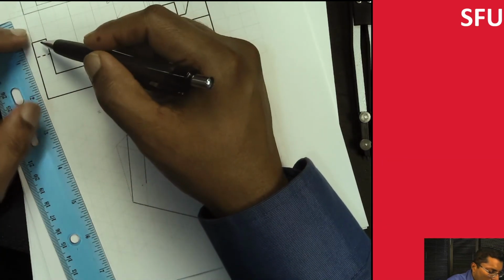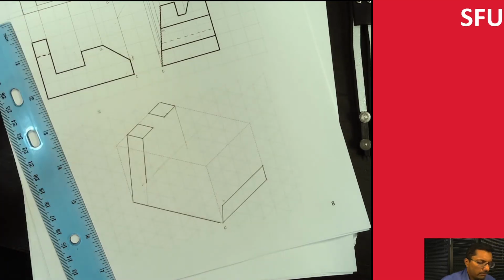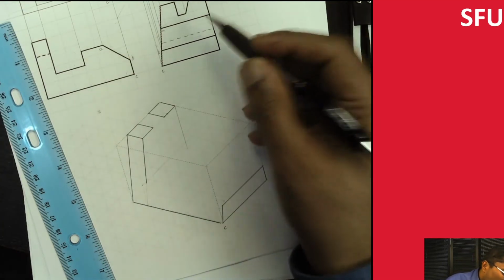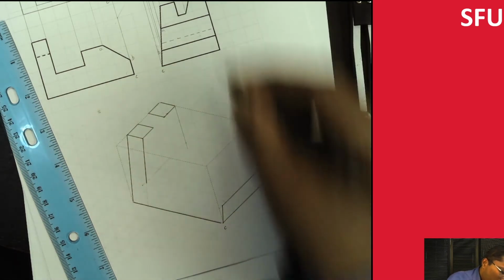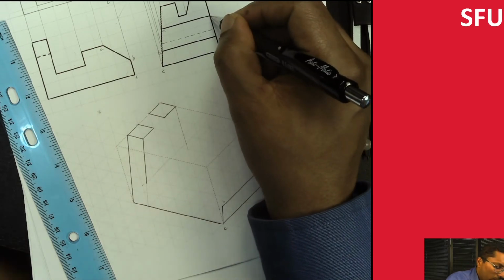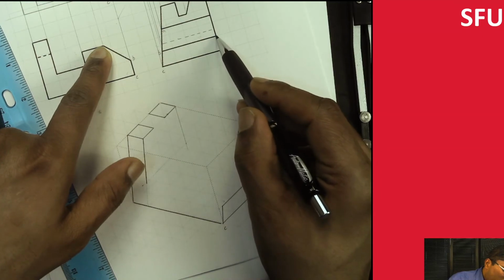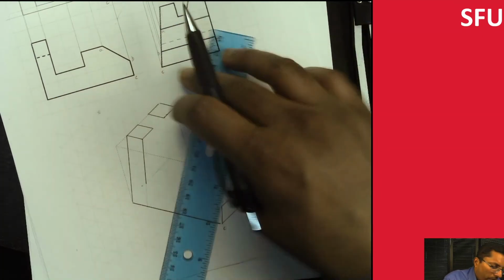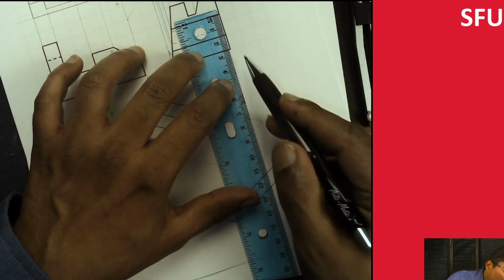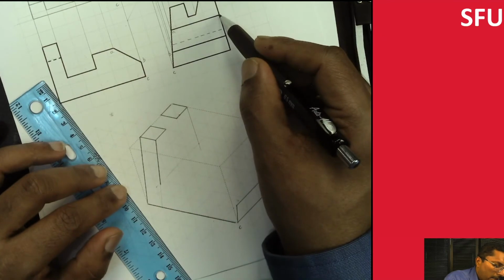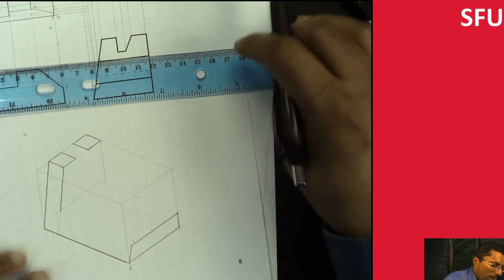So all right, we've done this and most of this face. So let's try to do this face, which again is a little bit complicated. The easier way to do it is to identify the location here. Where is this location? I have to look at two views. So I'm basically going to go 10, 20, then 25 millimeters. Again, I'm going to use the ruler over here. So this is 25 millimeters going vertically up. And then I can't figure out how far it actually goes to the left. So for that, I'm going to use the other view.